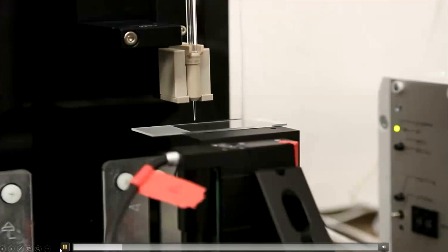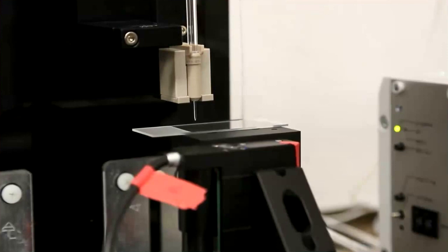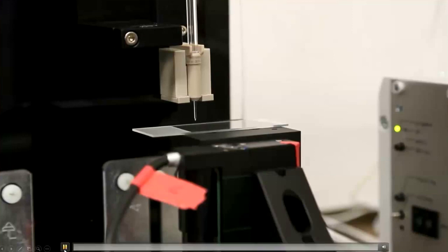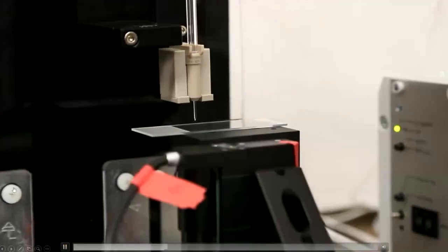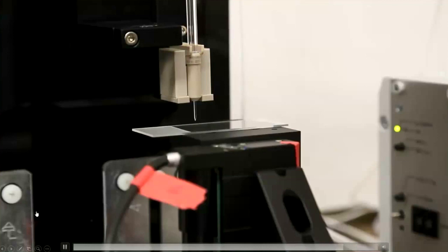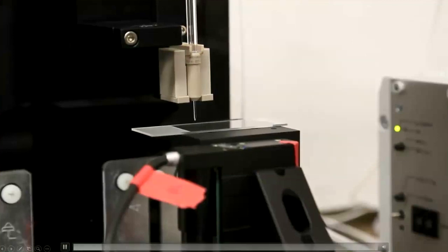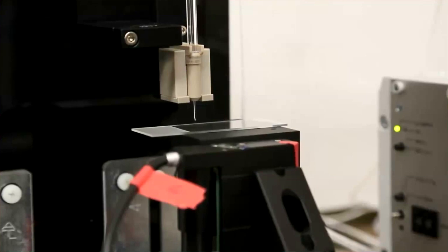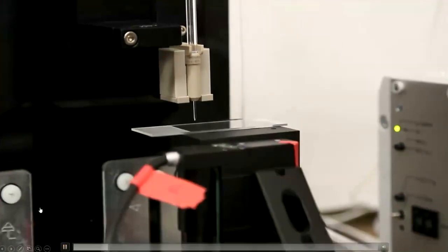Yeah. Okay. Oh, well, you took my punchline away from me, but the point being that watching micron scale deposition and array construction, you can't really see a lot, but if you look directly under the dispensing nozzle, and this is just onto a plain glass slide for purposes of enhancing what you can visually see, we're making a 125 micron by 125 micron grid here. That's about 10 microns thick. And just to calibrate you, the yeast that we're working with are 5 to 10 microns in size. So this is essentially a single layer. So next slide, please.